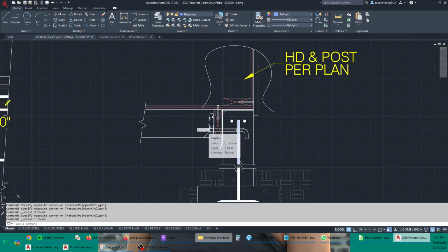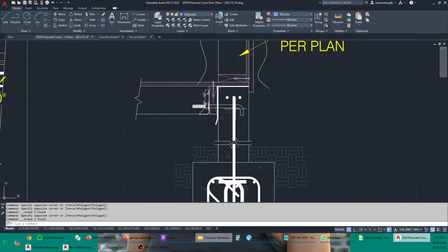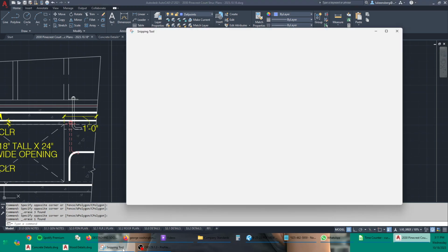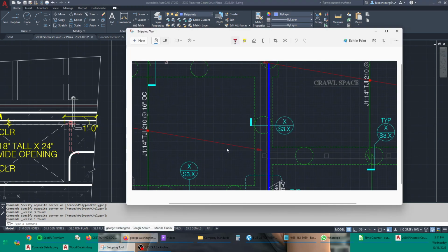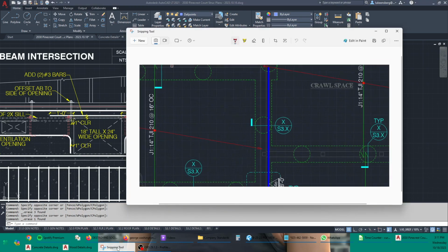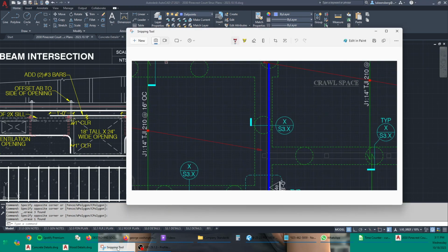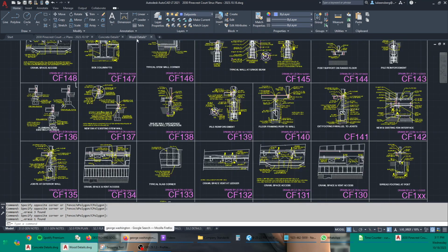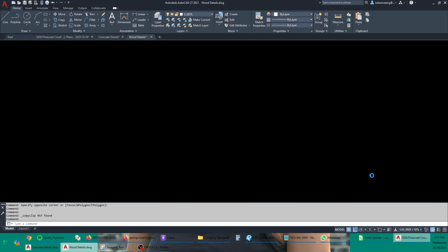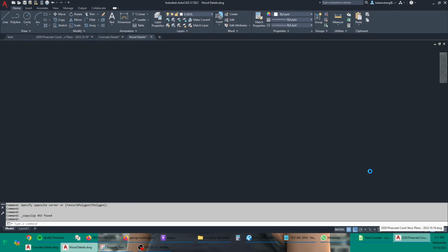And then the question is, am I going to have a concrete stem wall between the two wood floors? Let's see, how should I do that? I think the answer is no, I don't need that, and that's an engineering decision. Okay, I'll just stipulate that. So 14-inch deep joists, so I need to go to my toolbox and grab the image of a 14-inch deep joist.